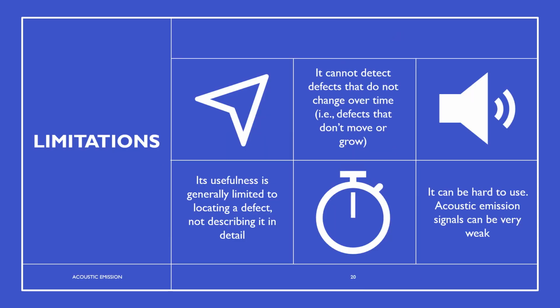Here are the main limitations for acoustic testing as a non-destructive testing method. Its usefulness is generally limited to locating a defect, not describing it in detail. That is, commercial acoustic testing systems can only provide qualitative estimations for the extent of damage found.